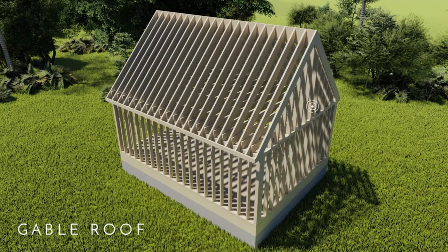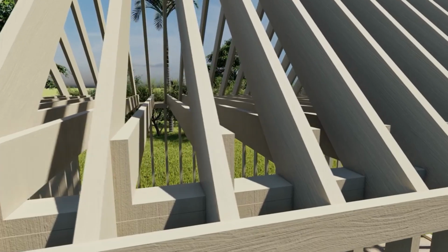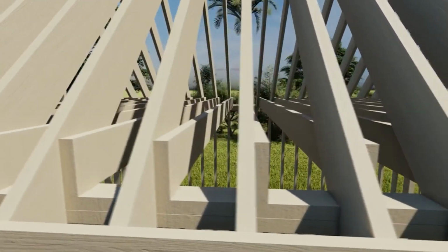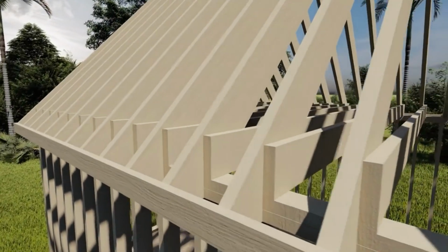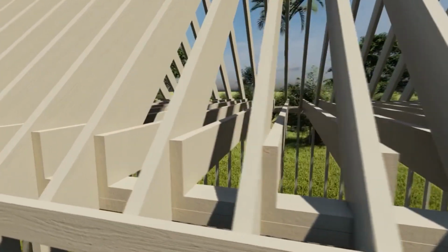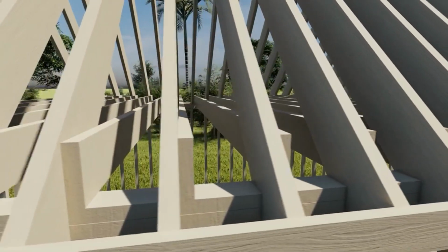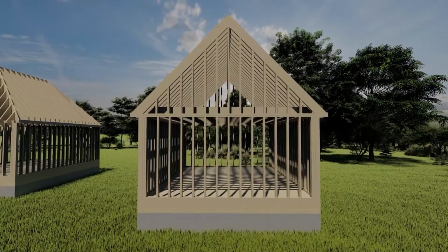When you have a gable like this, you end up with 2 attic walls, and these need to be studded. The distance from the top plate to the ridge will tell you how big of a roof rafter you actually need. Obviously, the longer the span, the bigger the roof rafter. This is the same thing with ceiling joists as well. And then you can see how the ceiling joists are connected to the side of the rafters.